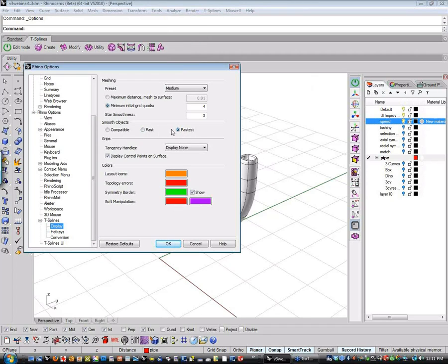Basically, in the fast and fastest modes they dramatically reduce the amount of on-the-fly smoothing happening over star points. That allows T-Splines to work in a lighter, faster, leaner version, which allows a much more instantaneous response to your user input.